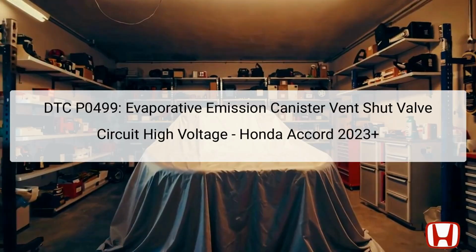The DTC P0499 pertains to an issue with the evaporative emission EVAP canister vent shut valve circuit in the Honda Accord models from 2023 onward. This code is triggered when the signal from the vent shut valve is on, although the powertrain control module, PCM, sends an off signal.